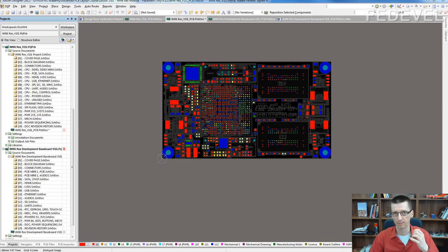It's 4 mils. And by the end of the design, I will change all the 0.1 millimeter tracks to be smaller to achieve the 50-55 ohm impedance. At this stage, it's still too soon to speak about this.